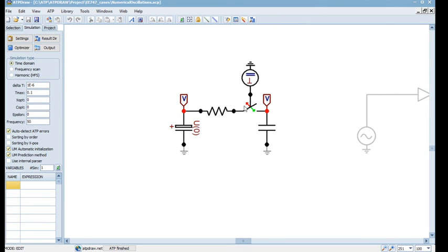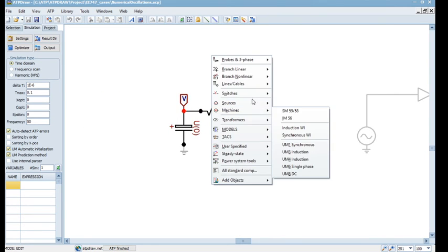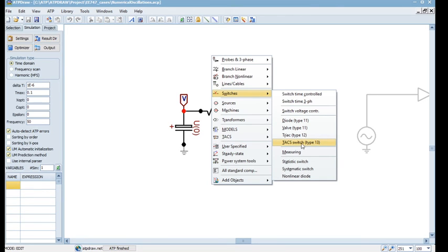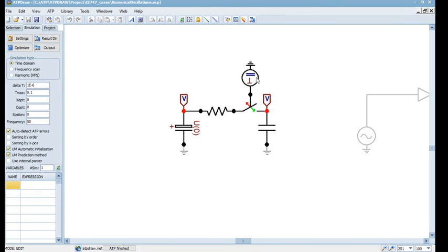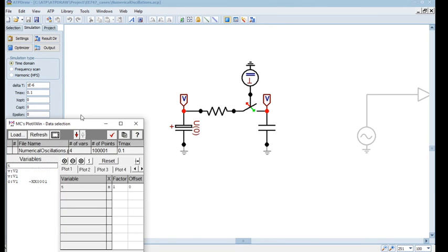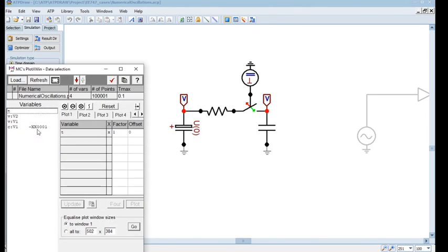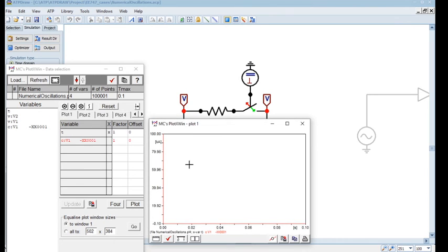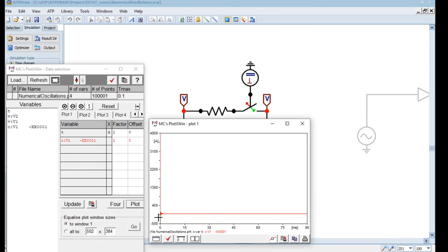See, this is the switch which I told you about. It's one of the switches which is easily controlled, so you control it from another source. And it's the same capacitor thing. The initial voltage you specify, and when you run this simulation, you observe some kind of numerical oscillations, right? So that's what it does. It's modeled in trapezoid. If you look at the current, the initial bump is like 100 kiloamperes, depending on the resistance value.